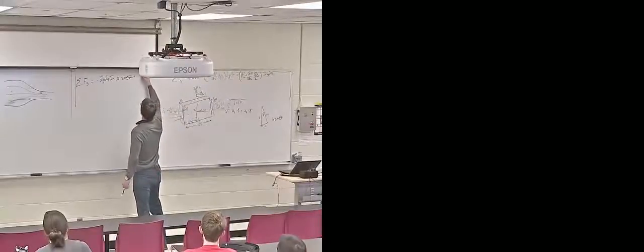We've got P naught minus P naught, and we've got a minus dP ds times ds over 2 plus another minus dP ds times ds over 2. So grouping these together, we should simply get minus dP ds times ds dy dn. Makes sense? Minus, you're right. Thank you.